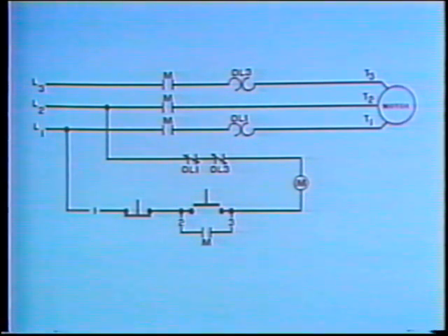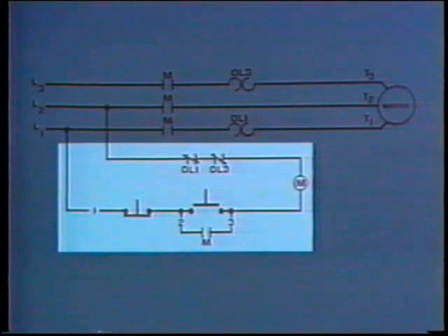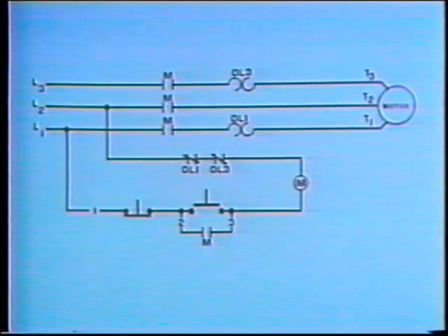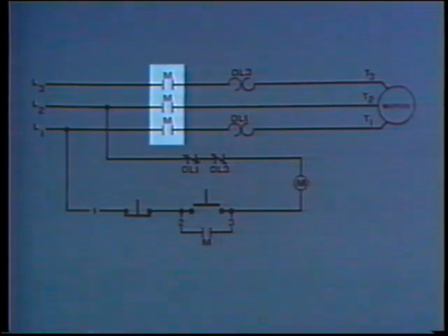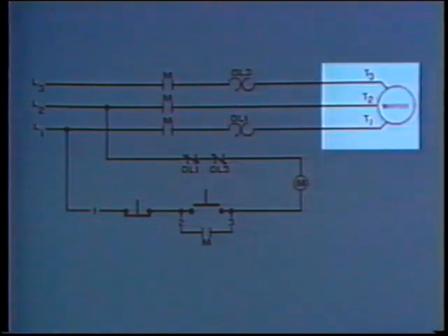First, he mentally divides the schematic into its motor circuit and its control circuit. Then he begins to conquer the problem by eliminating the working components in each circuit. In the motor circuit, there are three main contacts of the magnetic contactor, two overload heating elements, and the motor.